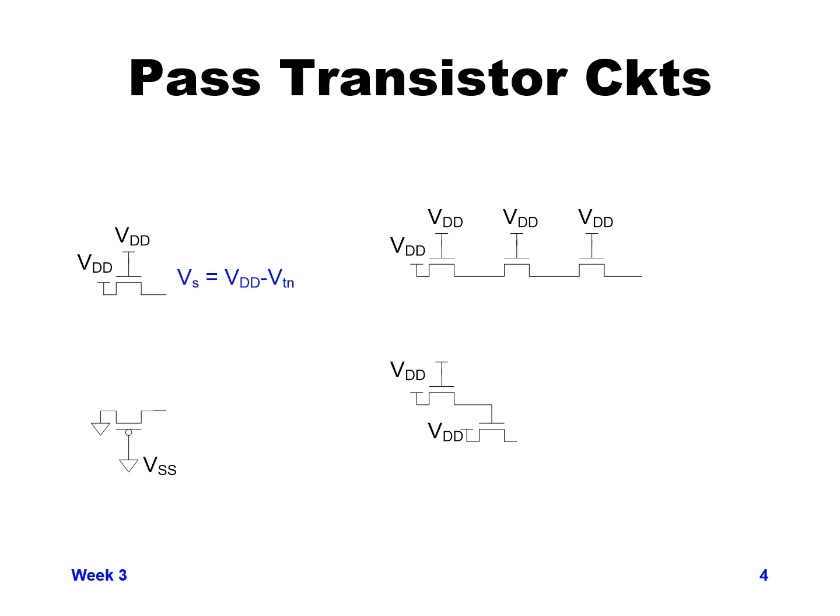Okay, so now that you've thought about that, what actually happens is the output of the first one will go up to a threshold voltage below VDD. The second one, since its gate is connected to VDD and the transistor won't turn itself off until you get to within a threshold voltage of the gate, its output will also go up to VDD minus VT.